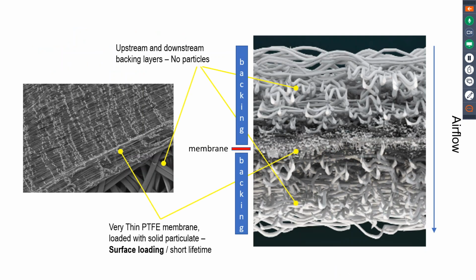Right, yeah, exactly. And because of that really thin layer, the PTFE loading, and again, that's why you have an oil-resistant version and a regular version. This is a regular version. In the oil-resistant version, all they've done is create another layer here, which is actually glass, oddly enough, microglass, where they've introduced it to try to steal the PAO away. So that's all it is: a layer of glass that's smudged in just over the PTFE layer to try to take that aerosol away before it touches the membrane. That's how they did it.